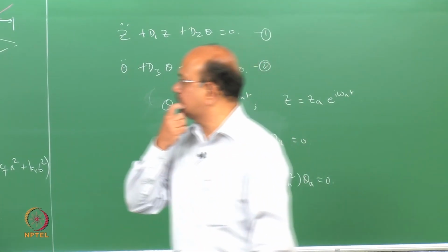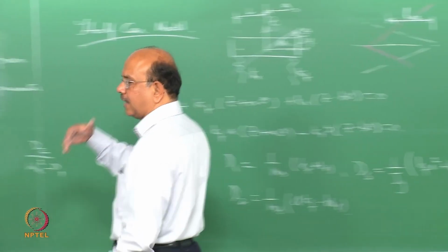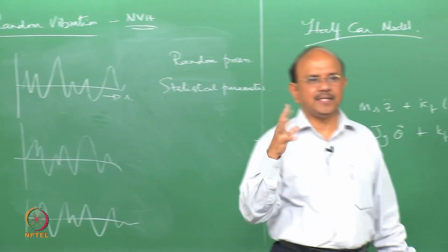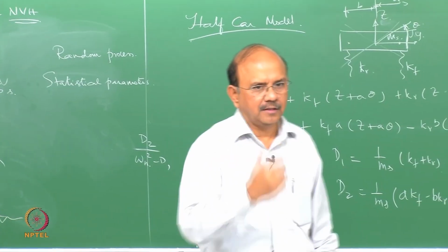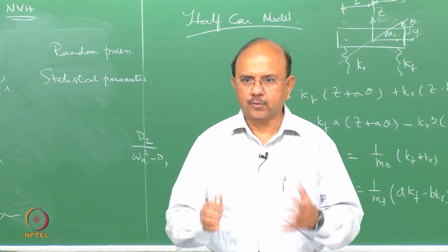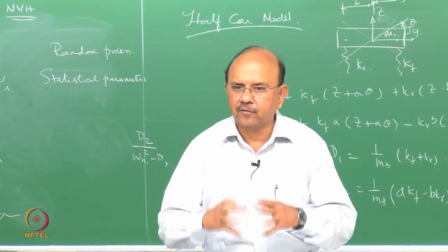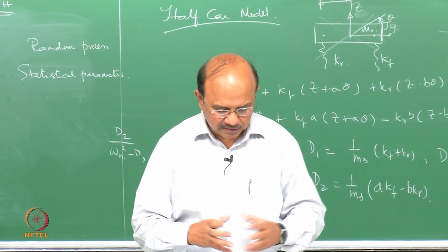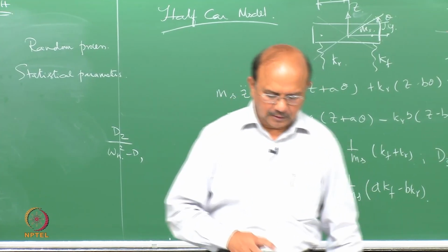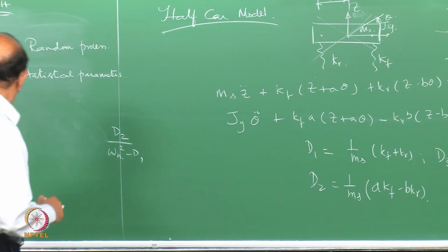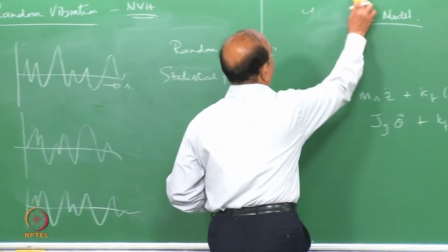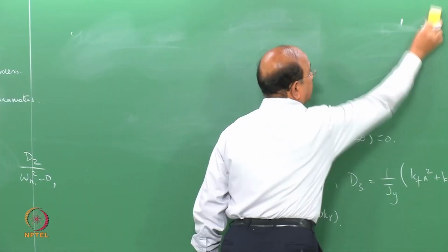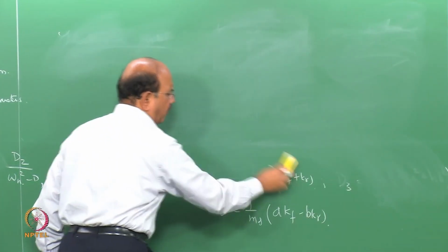How this is going to have an effect on the tire and so on, all these things become important. In other words, unless I characterize the input, I won't be able to study the output. So that's what I'm going to do. We'll go into a very short introduction to random vibration with random processes. Let us now define certain quantities which are common in probability, from where we will take off into random processes. We'll be slightly more formal.